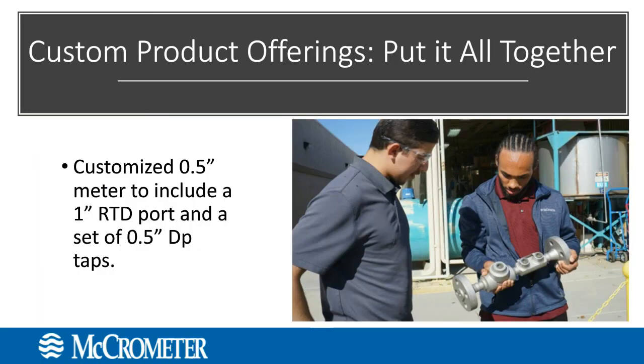So I just wanted to put everything together as to what we can do over here. I wanted to point out the picture to the right here. It's a 1/2-inch meter, so a tiny little meter, and it has the cone suspended in the middle, the same as the pictures we've seen of that large 78-inch meter. But it's also been made to include a 1-inch RTD, so an RTD that's twice the size of the pipe it's attached to, as well as 1/2-inch DP taps, which are the same size as the pipe it's attached to. The amount of customization there was key and crucial, with some amazing welding capabilities we have in our shop to be able to produce a really interesting looking meter, I think is the best way to go about it.